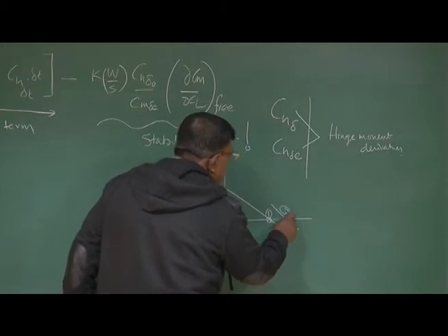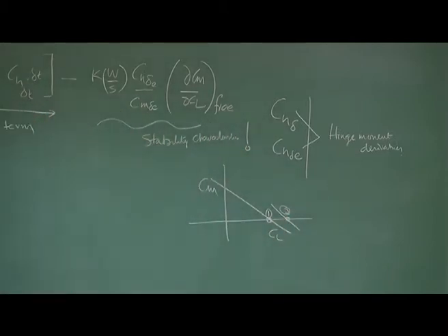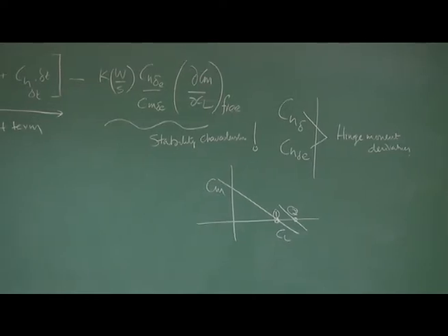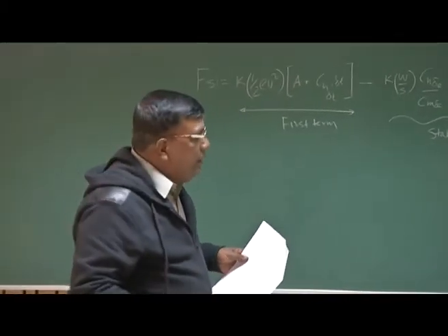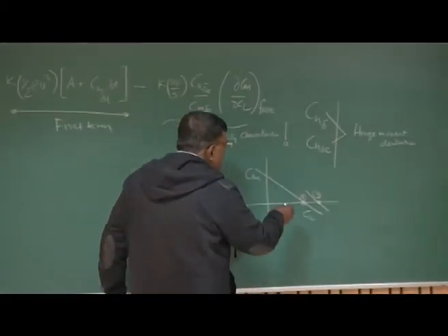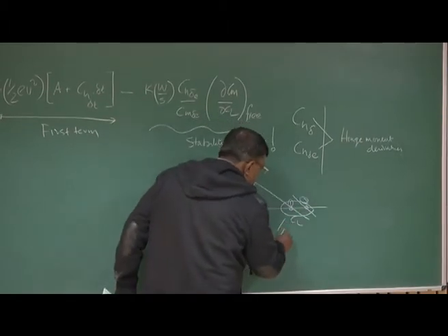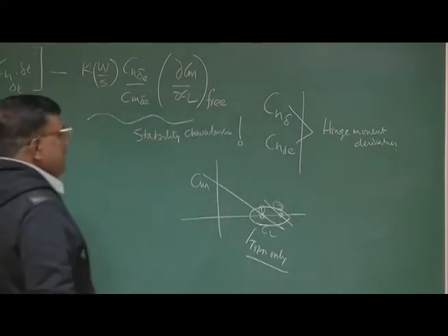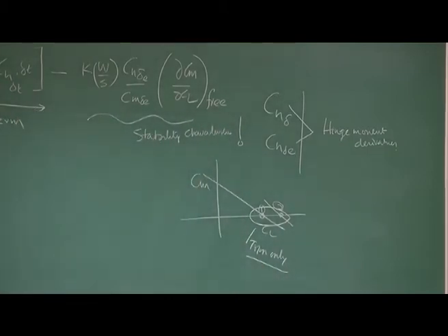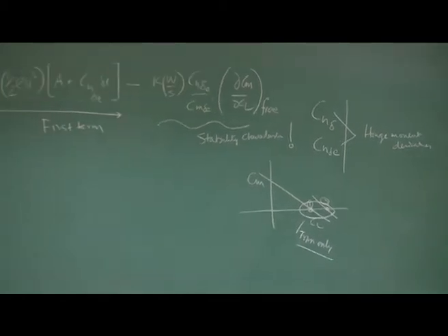So for the force requirement, or the gradient of force with respect to speed, I should be bothered about the trim only. And common sense says, if the airplane is highly statically stable, then this gradient will be large, because it will always resist.